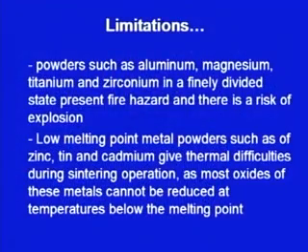Powders such as aluminum, magnesium, titanium and zirconium in a finely divided state present a fire hazard and there is a risk of explosion. Already we have discussed this in detail. Finally, low melting point metal powders such as zinc, tin and cadmium give thermal difficulties during the sintering operation, as most oxides of these metals cannot be reduced at temperatures below the melting point.